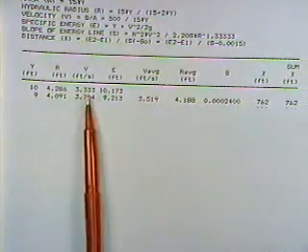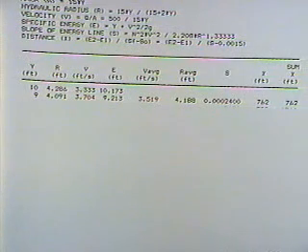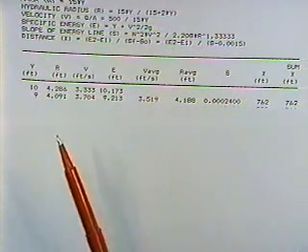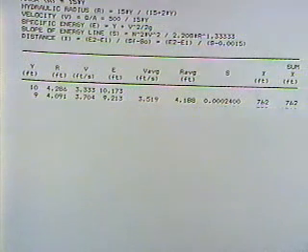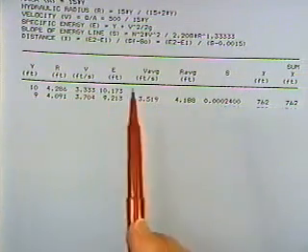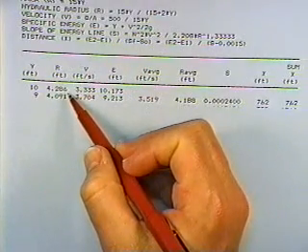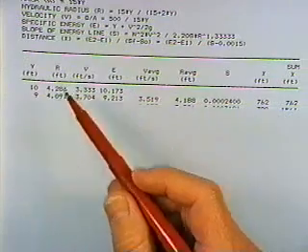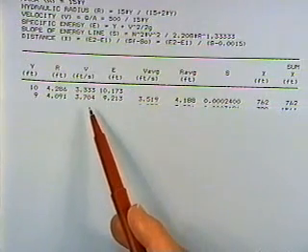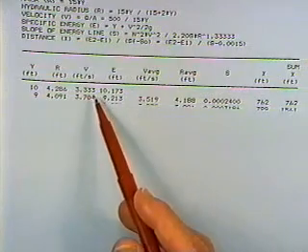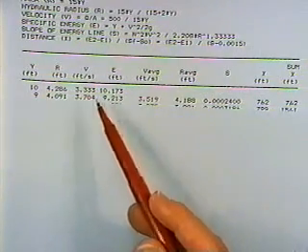We need the hydraulic depth, the velocity. The hydraulic depth is just the area divided by the wetted perimeter. The area is just 15 times y. The width is 15 feet, so 15 times y is the area. Then the wetted perimeter is just the bottom width plus 2 times the depth. We can divide one by the other, get the hydraulic radius each time, and divide the 500 cubic feet per second discharge rate by the area to get the velocity.